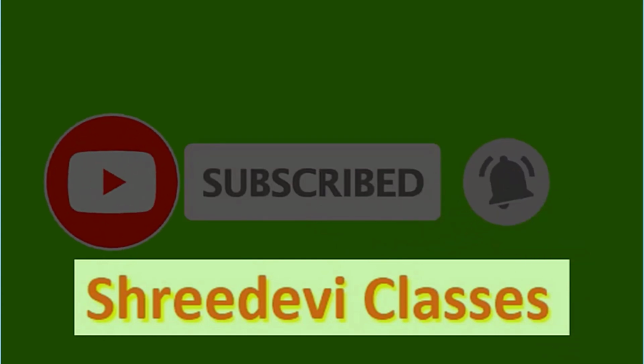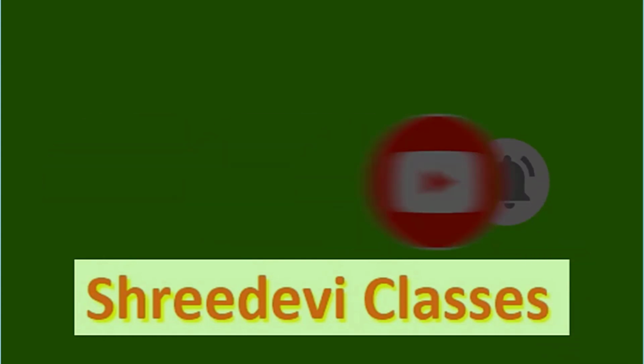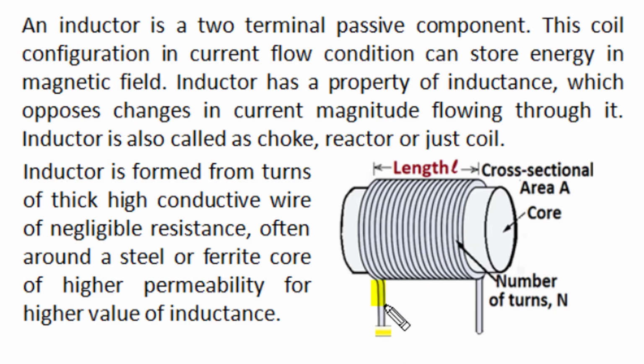So let's understand all about pure inductance behavior in alternating current supply. An inductor is a two-terminal passive component. This is a coil configuration in which, when current flows through these turns, they produce a magnetic field, and this inductor configuration can store energy in that magnetic field. The property of an inductor is known as inductance, and inductance is felt only when current is time varying. In DC current conditions, inductance becomes ineffective, but in time varying current conditions, this coil configuration or inductance opposes changes of current taking place in it.